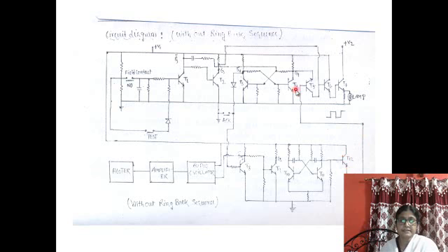This is connected, and it just produces pulse operation, a square wave generator. So this will send the pulse to the lamp, and the lamp will glow on with flicker, since this oscillation will be passed to the lamp side, and the audio oscillator will be turned on when this is in one state. So the hooter circuit will turn on.